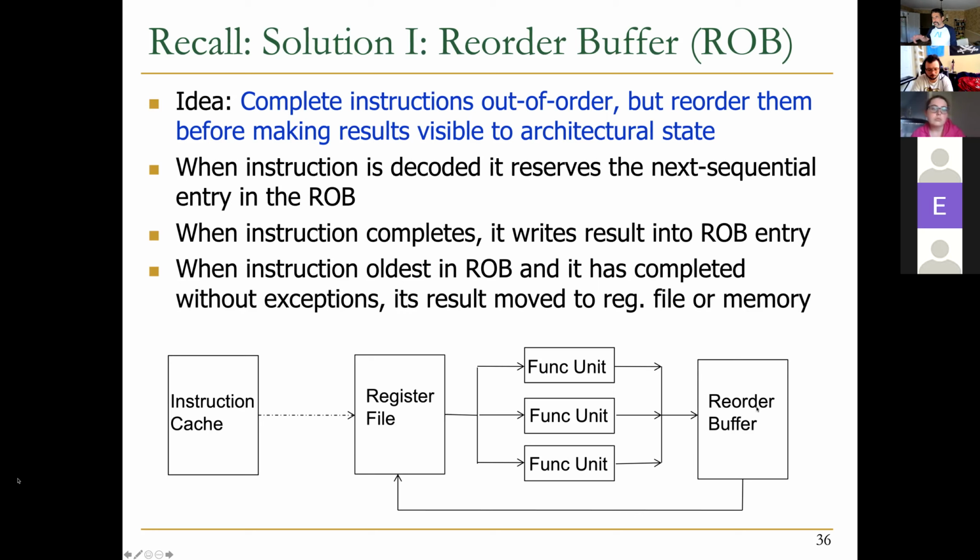And this reorder buffer makes sure that whenever the oldest instruction has its value in the buffer, it can be written to the register file, meaning that the programmer becomes aware of this architectural change. So again it is the same old trick of adding some construct, some hardware piece at the microarchitecture, which the programmer doesn't know about.